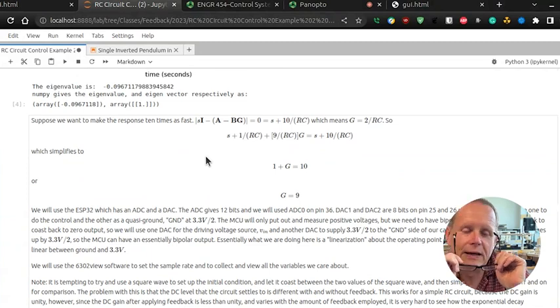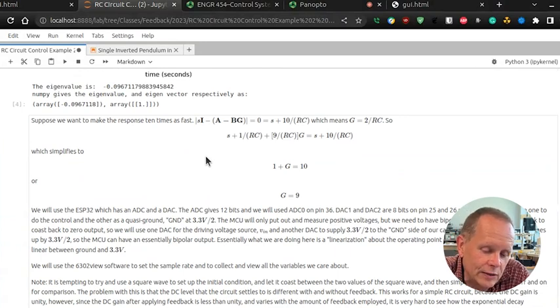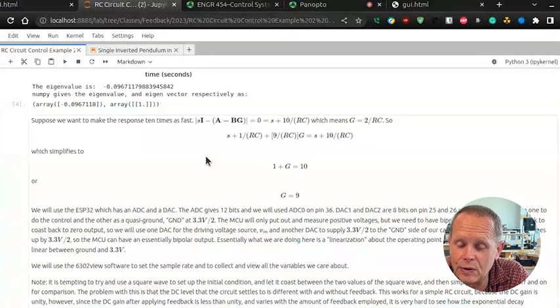In the next section, I'm using something called state feedback to determine how much I want to drive this input voltage with the DAC. Essentially, we're measuring the capacitor voltage, and based on that, I multiply that voltage by a factor of, I think it is 9, and then I subtract it from whatever was going in there before, and that's what the new input looks like.